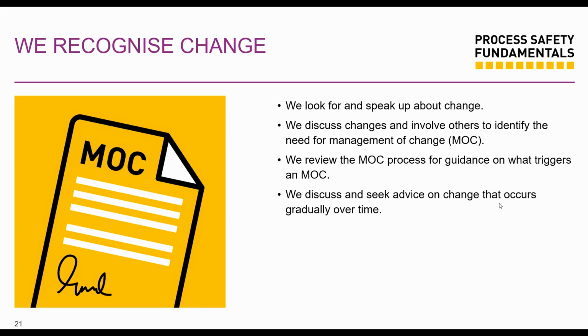Discuss and seek advice on change that occurs gradually over time. So review the MOC process for guidance on what triggers an MOC. Have that MOC process in place. This is so key, because hey, you had a valve here, you had a trip here, you had a vessel here, you had a pump here, and you're not properly capturing it in all the documentation, in your P&IDs, in your PFDs, in your plot plans, in your safe operating limit documentation.